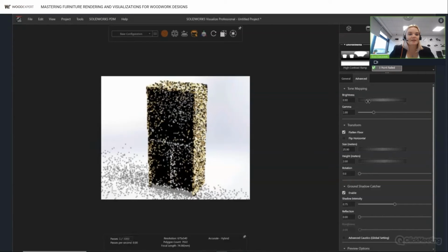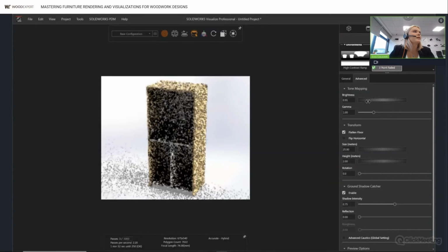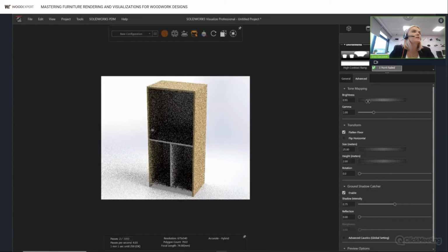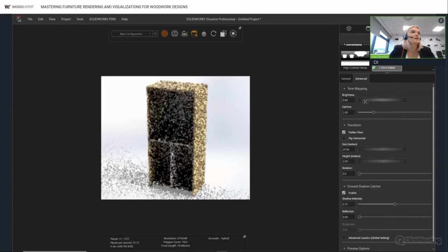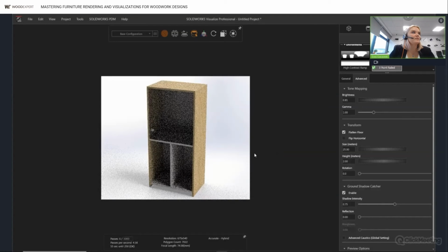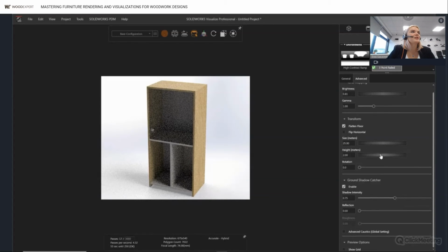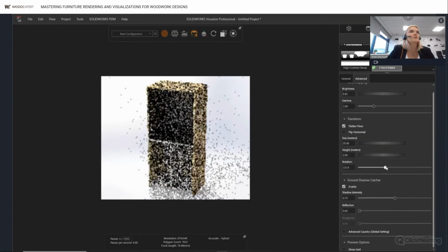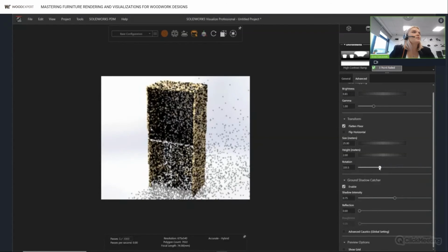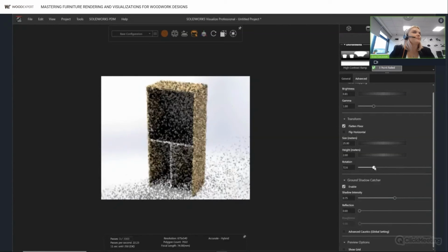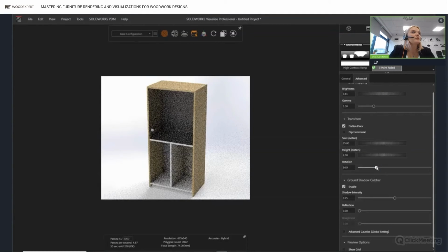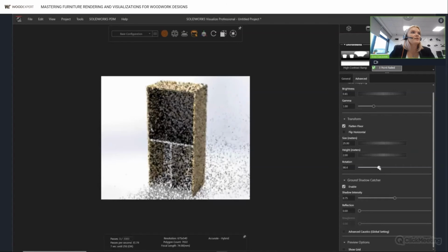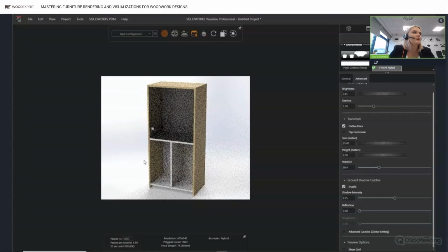So, scene and lighting settings. I use the finish scene and I do not change the background. I adjust the lighting of the model, and I advise against doing it on extreme settings. It is better to change the brightness of the material so that the effect is natural. An important parameter is the angle of rotation of the light, so as not to overexpose the materials and to show their structure.